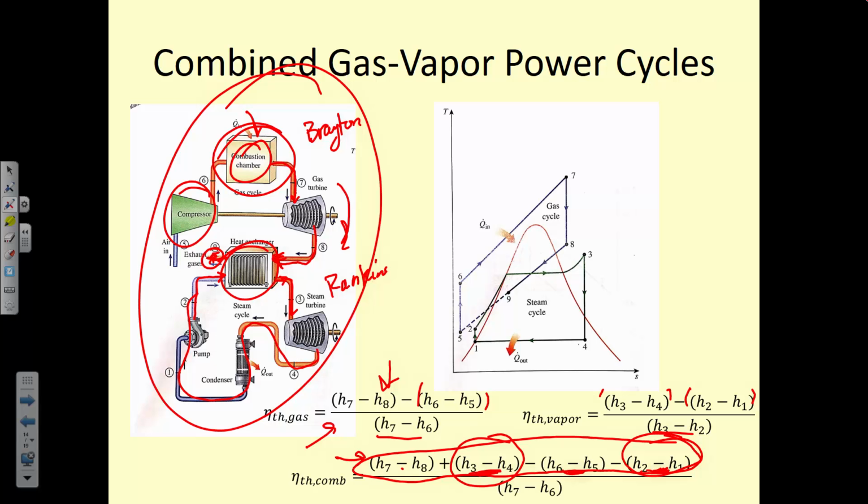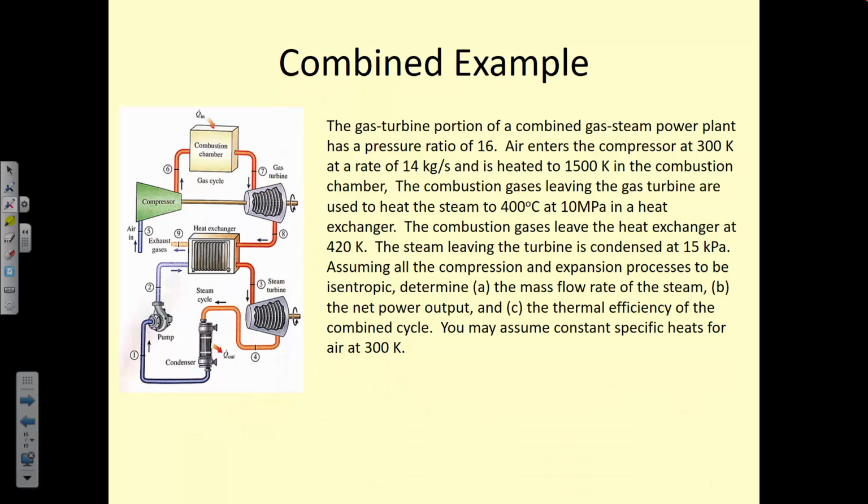So we have high exergy at a high temperature, and if we were to just quit right here, then we will have converted not very much of it to usable energy. But by changing working fluid, using that heat now in water instead of in the gas cycle, we can regain some of those losses. It's kind of exciting, I think, right? Just agree with me. It's better that way.